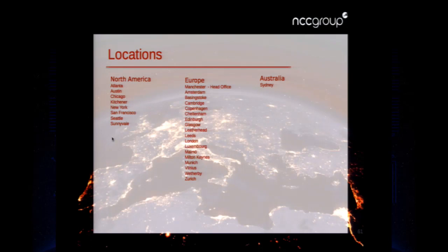If you're taking out all the decoupling caps in a full-blown system, I would think that would be really dangerous. Yeah, it's pretty dangerous. You want to take them out around the thing you're targeting, though. That's the general idea. You definitely don't want to take out the decoupling caps near the crystal if you're just doing a brownout attack. But any of the power decoupling caps near the thing you're targeting, you should try to take out. But you want to do that slowly.